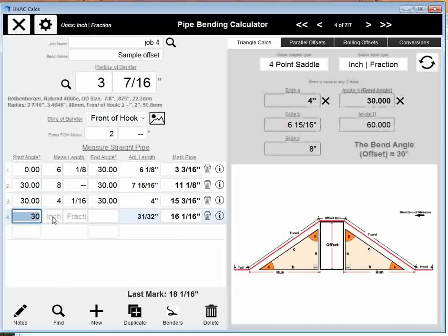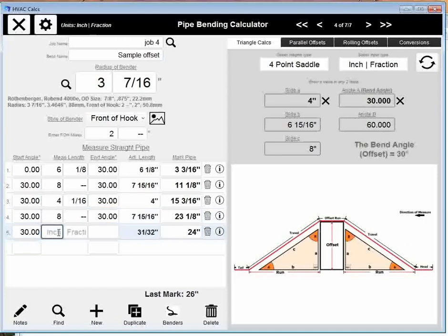And then we're going to have another, again, your side C coming down is going to be 8 inches to another 30-degree bend. And then your tail piece, let's just say it's 9 inches. Who cares? 9 inches and 0. And again, you're going to have a total length of pipe of 33 inches.